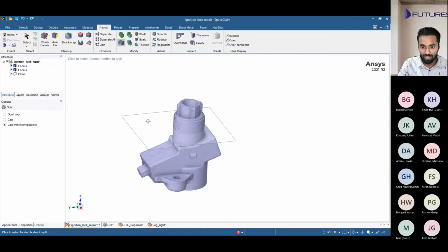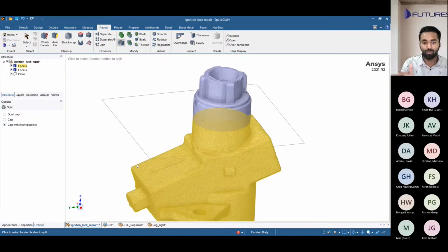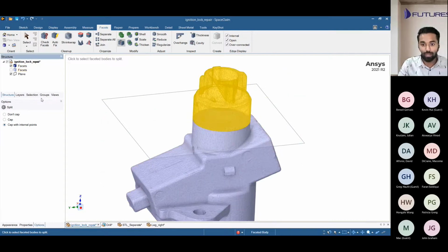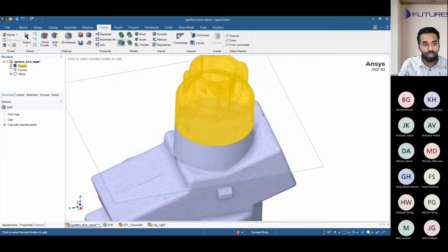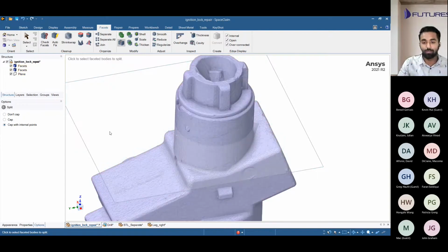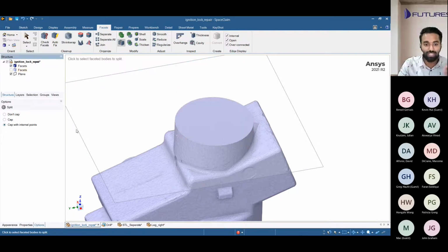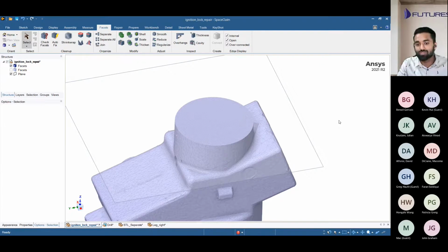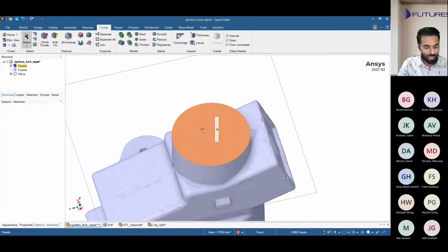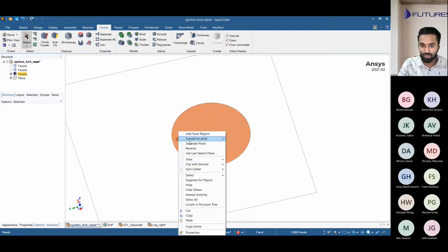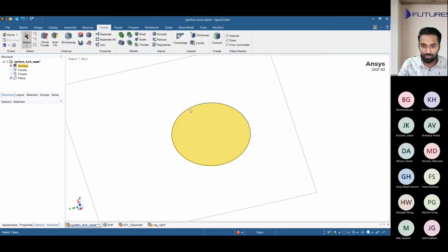So as you see, we had a problem that our printer was not able to accommodate this size of a print, so we chopped off our part. But the problem that remains is, if we have these two different parts printed separately, how will we align them? It will be quite difficult, right? So sometimes we need some kind of a key through which we can align them, right? So I'll just go ahead and edit this. Let's see if we are able to get something out of it.